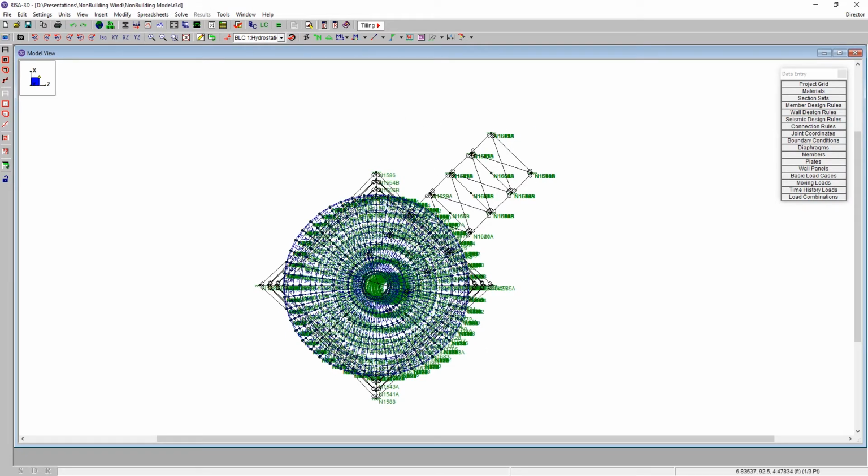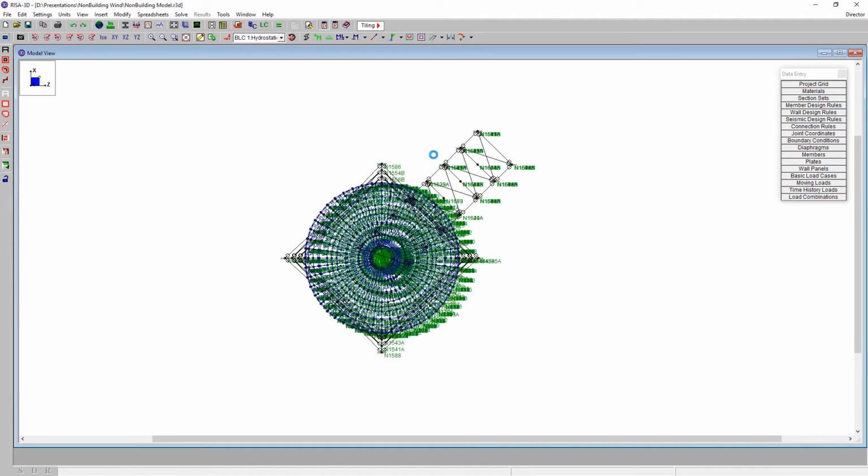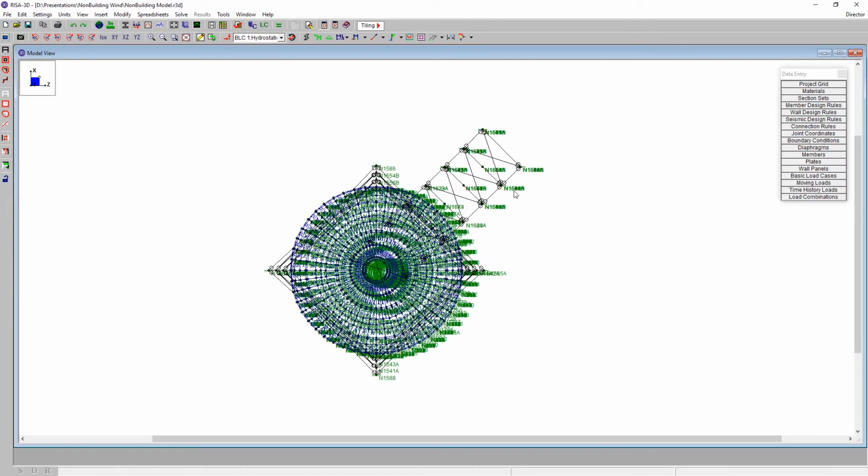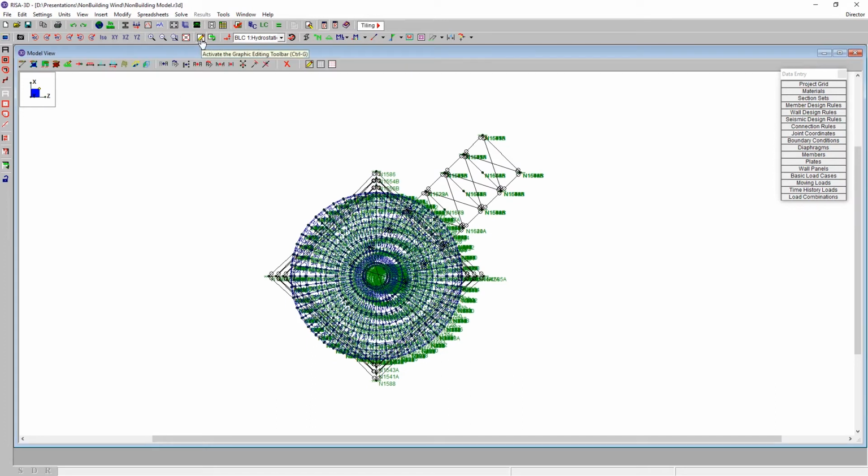It's at a 45-degree angle from any orthogonal global axes. Having this skew actually is not very useful for me in this case, because I want to be able to consider wind acting perpendicular to these surfaces. And in order for me to apply wind acting perpendicular, I'm going to have to break it into components, apply those separately. That's a lot of work that I don't want to deal with. So one thing that I might do here is I might take this whole structure and just rotate it so that we then have the structure aligning with the global axes.